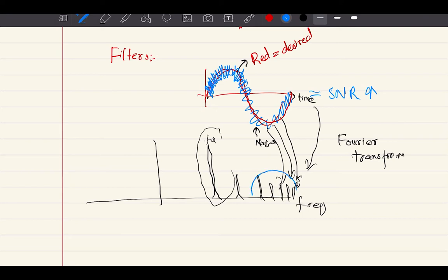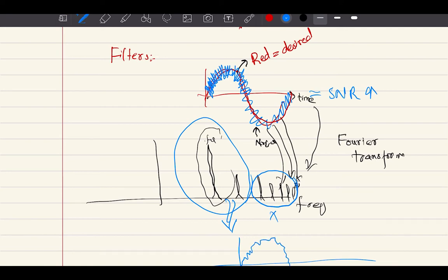So any high frequency which will be contained there in the frequency domain, we will simply discard it, and we will only keep the frequency which is belonging or very close to the fundamental frequency. And after doing that, if we recover the signal back to the time domain, it will look very clean, or it will be looking like this.